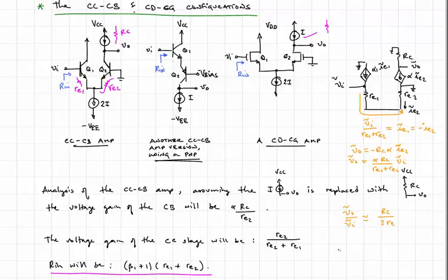And additionally, the quiescent operating point is for VI to be at 0, not at some DC voltage. Of course, you could change this if the base of Q2 was not tied to ground, but instead tied to some other voltage, say 1 volt, then the quiescent point would be VI equal to 1 volt, and so this is a big advantage.